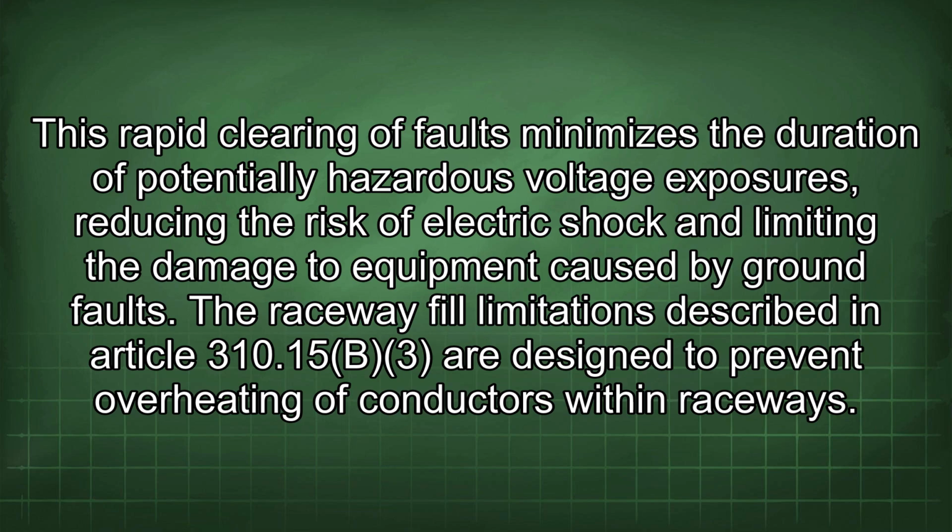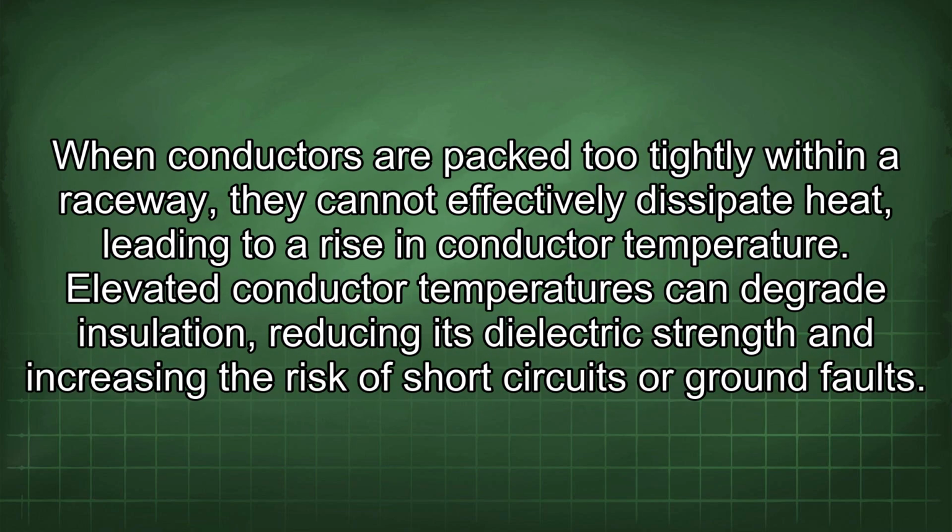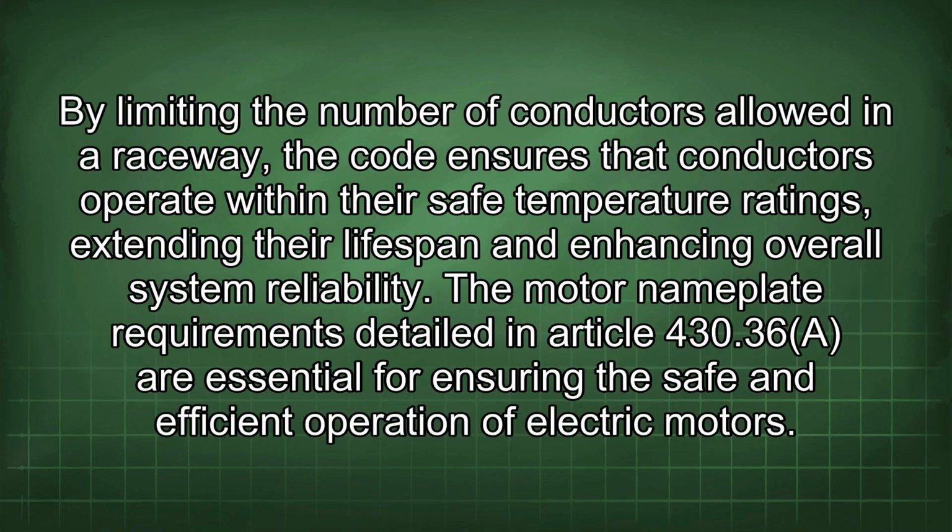The raceway fill limitations described in Article 310.15b3 are designed to prevent overheating of conductors within raceways. When conductors are packed too tightly within a raceway, they cannot effectively dissipate heat, leading to a rise in conductor temperature. Elevated conductor temperatures can degrade insulation, reducing its dielectric strength and increasing the risk of short circuits or ground faults. By limiting the number of conductors allowed in a raceway, the code ensures that conductors operate within their safe temperature ratings, extending their lifespan and enhancing overall system reliability.